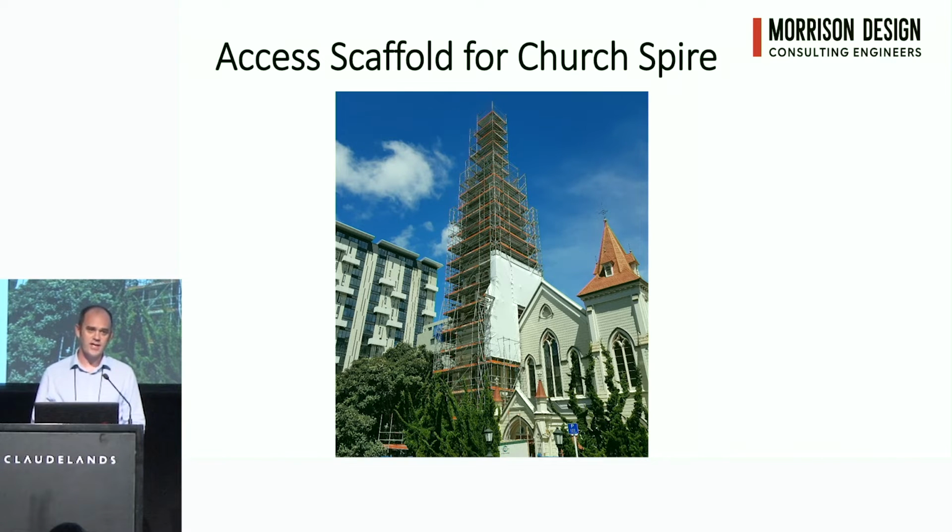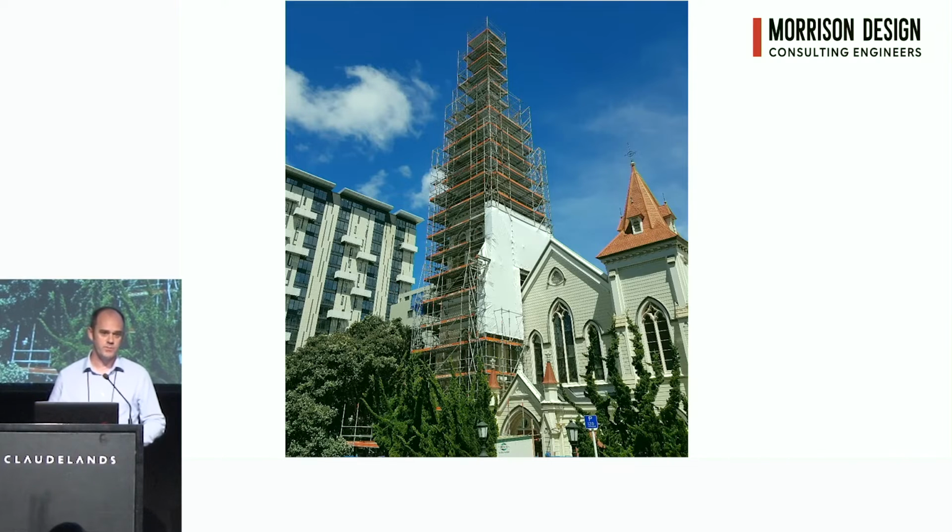The contractor had a request to install a cloth scrim around the top of the scaffold. However, the wind loads were going to be too much for that. The spire wouldn't support it, and the scaffold wouldn't either. So instead of having that cloth scrim to catch any equipment which might accidentally fall off the scaffold, a catch fan was installed to the lower section of the scaffold. The catch fan was put out every day that they were going to be working on the top section of scaffold, and then each night after they'd finished their work, they brought the catch fan back in.